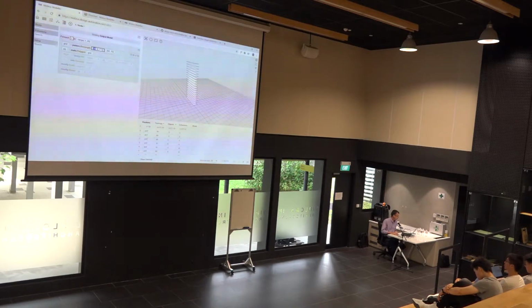35 meters in the x direction, 0 meters in the y direction, and I times 5 in the z direction. I is this loop. Here you're looping through, and this is the I. The first time around the loop it's 1, and then it's 2, and then it's 3. That is why this thing is going up. Each one of these polygons is 5 meters up.